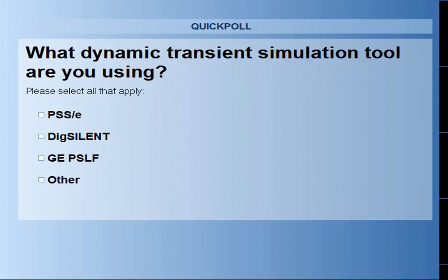And for that size of the grid, we obtain a simulation performance between events, between faults or switching events, of 3.28 milliseconds of real computation time for a 10 milliseconds simulated time, which places us well within the real-time range for such a large network.